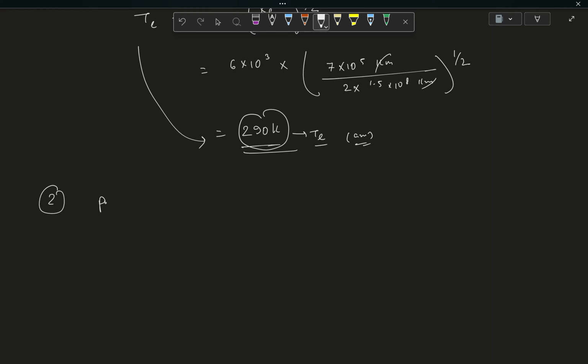So second is about an optical pyrometer. A pyrometer is basically a particular instrument that you use to measure temperature. Normally you are familiar with a thermocouple, which measures temperature by taking a temperature difference and generating a voltage, and that electrical voltage gives you an estimate of the temperature difference, from which you can estimate the temperature. That is the thermoelectric effect or Seebeck effect, used in thermocouples to sense the temperature.